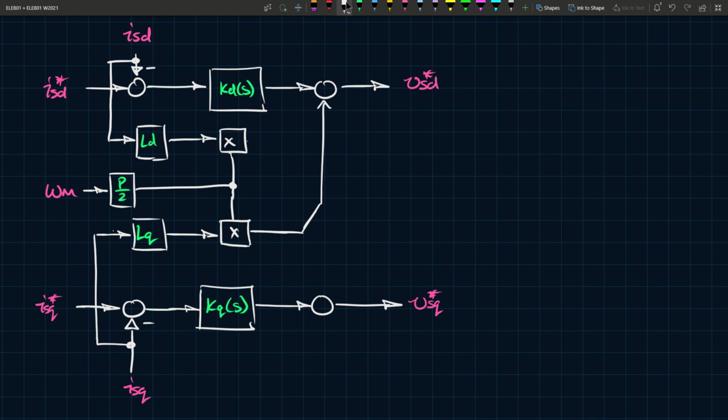So now those crisscrossing signals end up causing issues because they result in coupled behavior. So one control signal depends on the other. Now, that's obviously not ideal, and not that it's not ideal, it's actually very bad. So we try to decouple, and in order to decouple, we have to use what we call feed forwards.